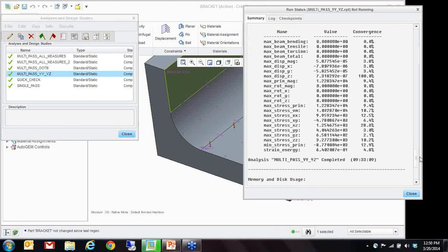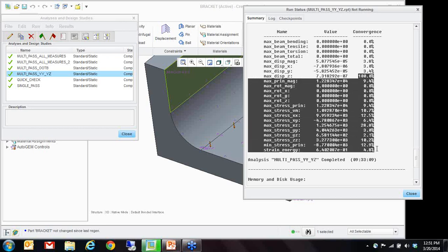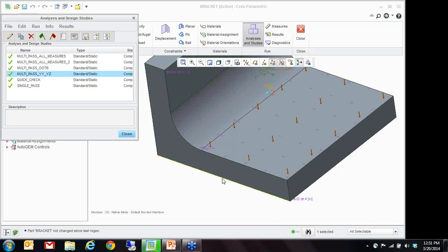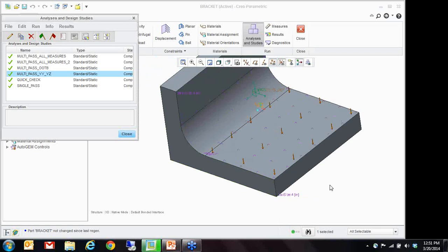Okay. So now I'm going to look at the results for that. When you look at the results, you could directly see here some of the results were crazy. None of these others are getting converged within those percentages except those two. Those two are within 5, but you have a whole lot that is kind of out of sync. Again, I am not worried about stress values yet. I'm just looking at the percentages.